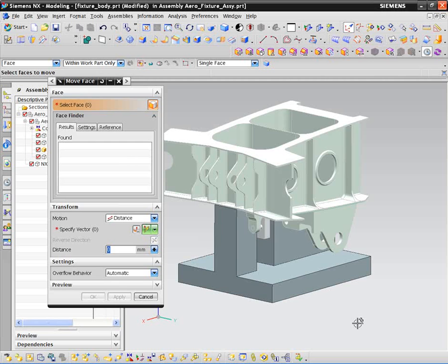But we often find, especially in fixture assembly modeling, that associativity is overlooked or isn't taken care of, because in so many cases these fixtures really do not get reused. It's not all that common to come back and do this kind of work again. So in lieu of associative construction, we've got these other tools that can quickly get us a reusable condition.